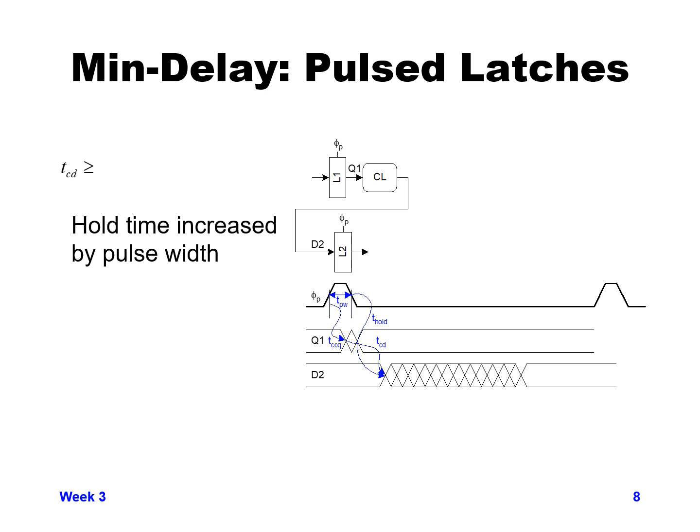In this particular case, it's clocked by the same clock as latch 1, and that closing edge depends on exactly how wide your pulse width is. So if you have a fairly wide pulse width latch, you can see where that closing edge could be getting close to that time for D2.